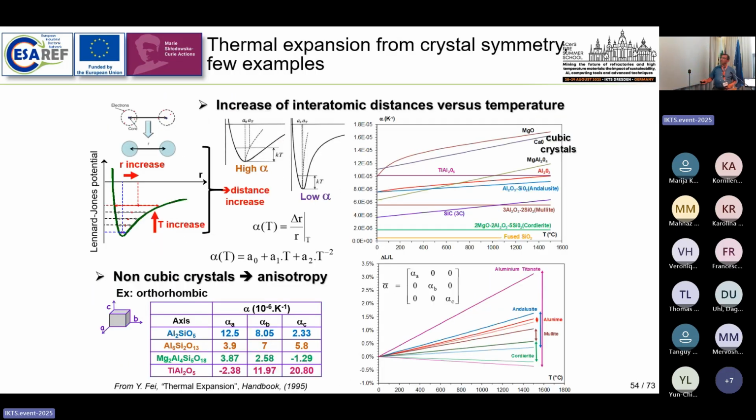Of course, playing with those kind of systems, it is very interesting to check all the different values of thermal expansion. I also incite you to check more carefully thermal expansion values because usually people consider, okay, the thermal expansion value of alumina should be about 8 or 9. But in fact, if you look carefully at the documentation, this is absolutely not like that because the thermal expansion is not constant and depends on the temperature range. If you look at the thermal expansion of alumina, it starts at 8, yes. But at high temperatures, it is much larger than 10 because the thermal expansion is not constant.